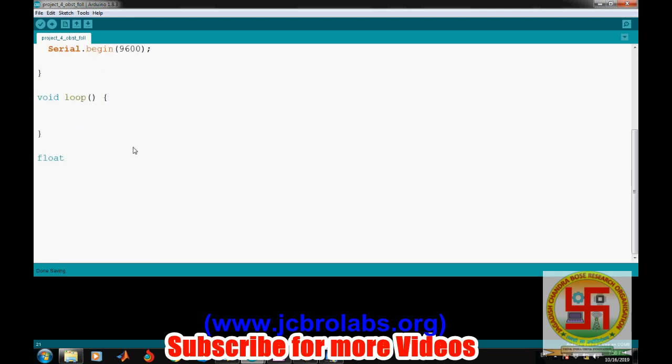Okay, and then it should return the value. So here we can write it like calculate distance, and it should not take any argument, because as soon as we call it, it should return us the distance. The procedure of calculating the distance from the ultrasonic sensor is we send a high to low pulse of 10 microsecond duration on the trigger pin.